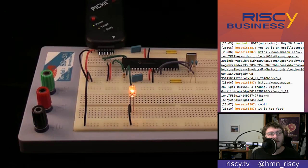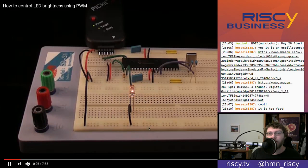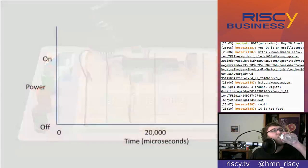Them on and off. To control the brightness of an LED, you can vary the power which is sent to the LED. The more power the LED receives, the brighter it is. The less power, the dimmer it is. However, microcontrollers are digital, meaning they only have two power states, on and off. PWM provides the ability to simulate varying levels of power by oscillating the output from the microcontroller.